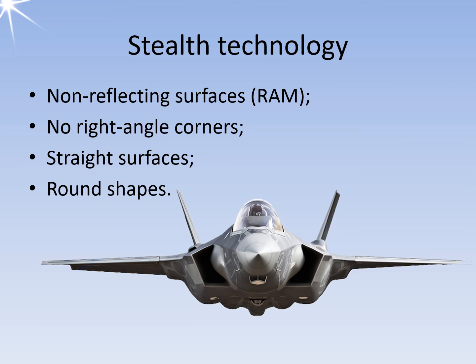The engine openings must be positioned so that the radar does not detect the engine blades. But all these measures only work if the wavelength is significantly smaller than the surfaces. Stealth technology is ineffective for very long-wave radar sets. This has led to a renaissance of VHF radar sets.